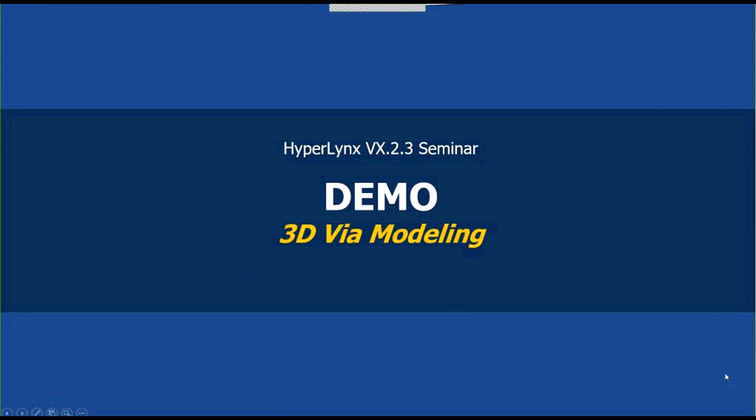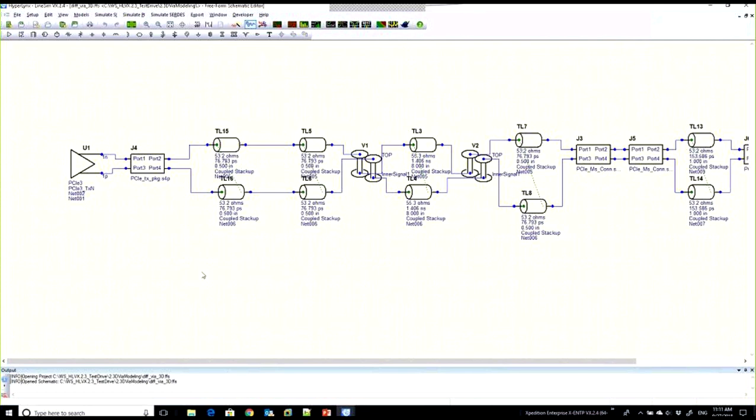So let me go ahead and bring up a LineSim design here. So we've got our differential driver. There's a package that differential driver is inside of, so it could be an FPGA package or whatever. It gets to the board. There's some traces that go along. They change impedance a little bit here, not by much. And then they go through a via to a different layer and then come back up to the top layer and on and on. I'd like to get a little bit more accuracy with this via model here.